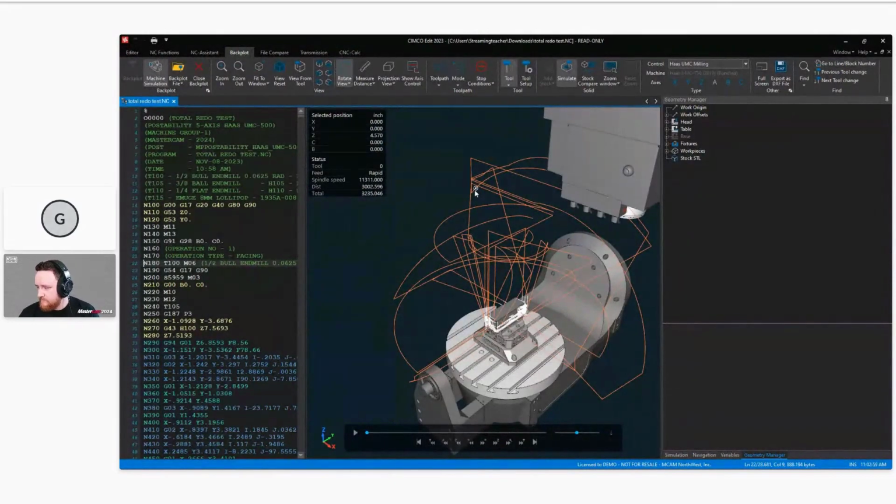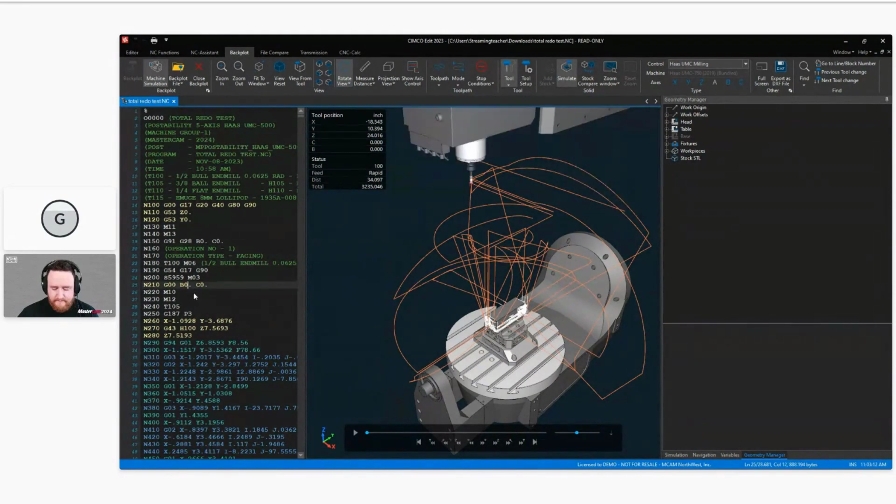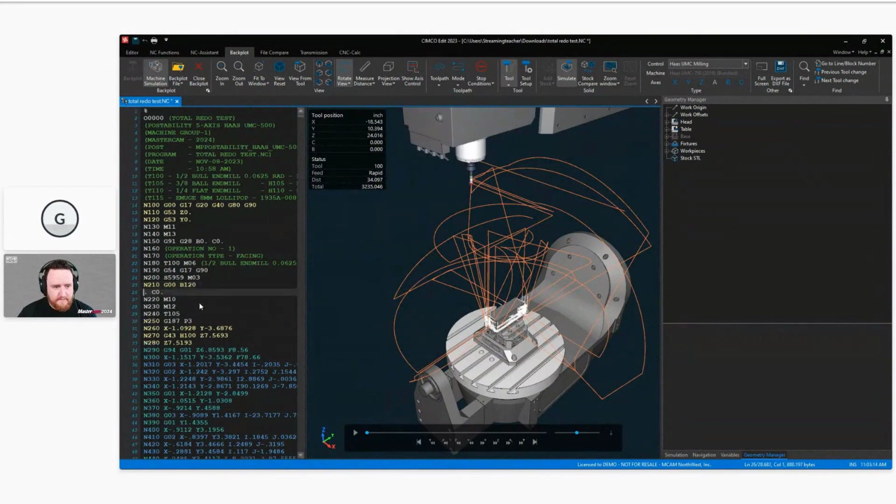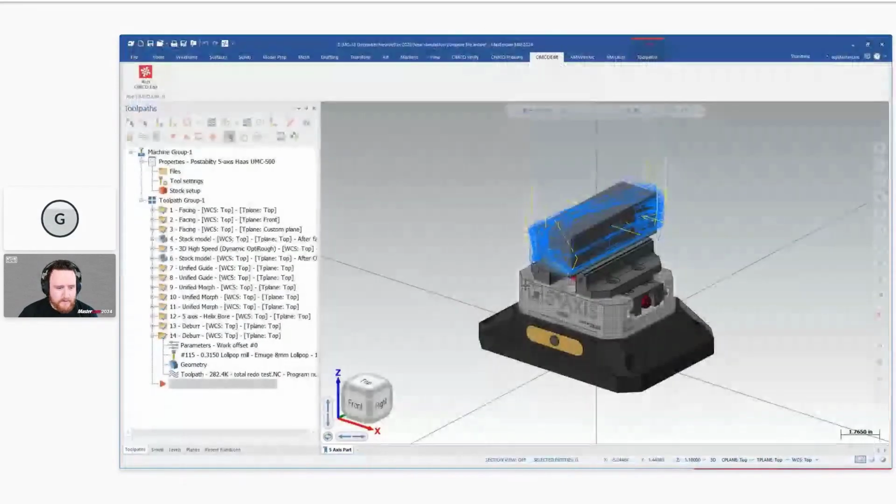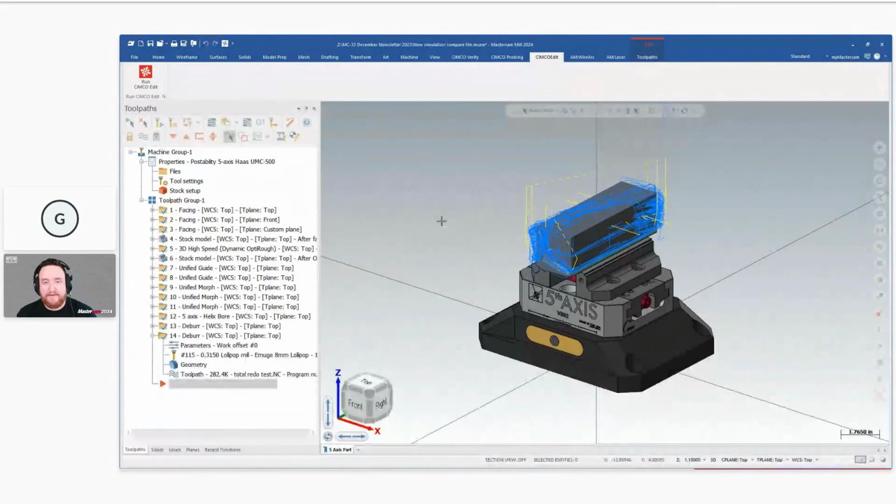Also, because it is reading the G code there, you could go in and fat finger a motion, a new move in there, and it will follow that. Indeed. So, like if you went in and changed one of those B0 rotations to like a B120, just to, oh, you have to put the C. I did something bad in code and I killed it, which is my fault, not its fault. But yes, you can actually modify those values directly.